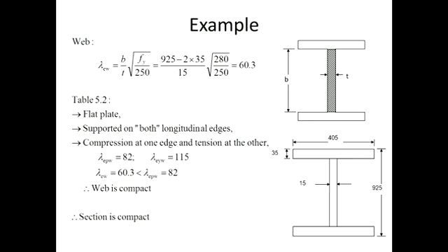But maybe a question would be what would be the section slenderness for this I section. Then you have to look at the values of lambda E over lambda EY, and whichever is the greater of those two within the section will be governing your value of lambda S.